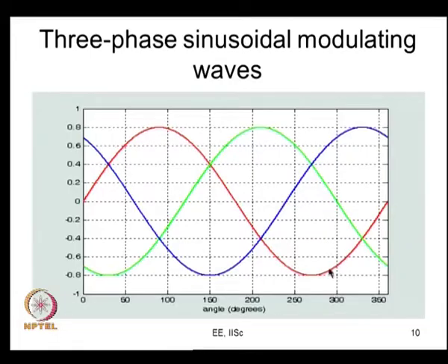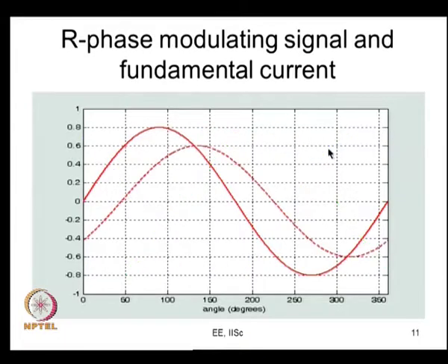So, I am considering sinusoidal modulating signals. There is some voltage VDC, and I am considering some sinusoidal modulating signal. Incidentally, let us say 1 and -1 are the positive and negative peaks of the carrier, the modulation index is 0.8, the sine peak is 0.8 times the carrier peak here. So, this is sine triangle PWM, you have 3 sinusoidal signals for R, Y and B phases.